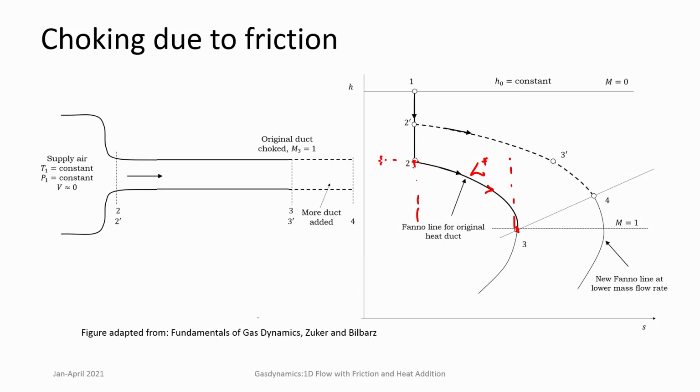So, that is also not going to change. Then the only change that can be done here is to vary the duct length. So, to vary the G, that is mass flow rate. So, if mass flow rate is varied, then G can change, G decreases.